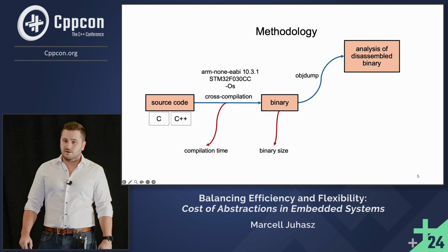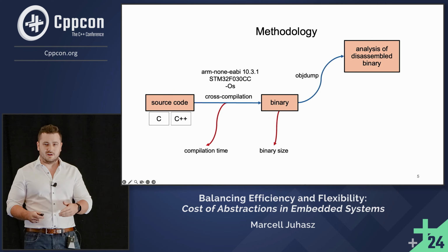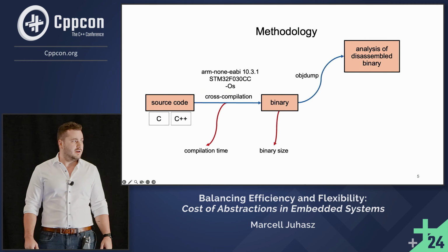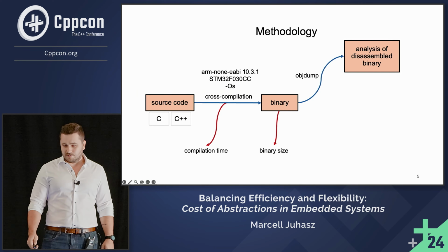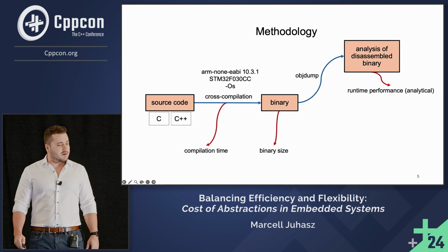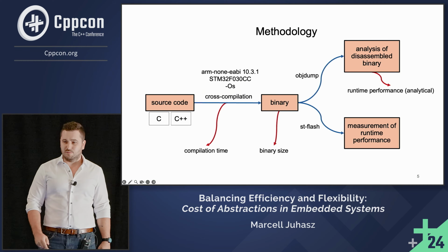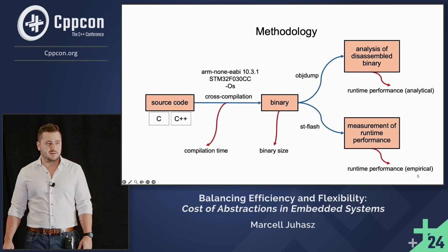Then, on one hand, I went ahead and I analyzed the disassembled binary. I wanted to see what actually gets executed on the microcontroller, and this way I could assess the runtime performance in an analytical way. And for getting empirical results, I flashed the target, I executed the firmware, and I measured the execution time on the target.